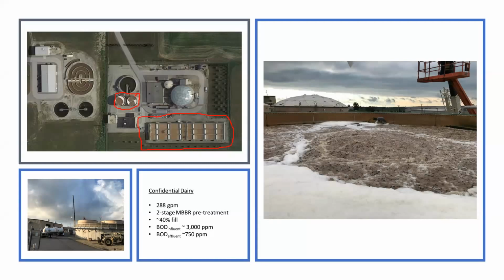Even with a fine bubble system in dairy, it will be inevitable that the diffusers will have to be cleaned or replaced, and it varies from site to site. In this case, the client elected to go with a more standard coarse bubble system. That's what we added to the process, just to minimize maintenance in the long run.